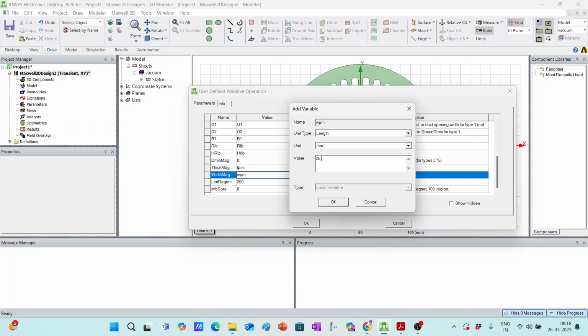Now one thing to tell, as it is a V-shaped magnet, V-shaped IPM, the combined length of each leg of the V will be the total magnet length. So there will be two parts. One part will be the left side of the V, one part will be the right side of the V, magnet part. The combined length you have to put here. That is the magnet length.